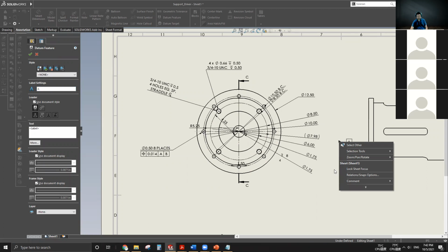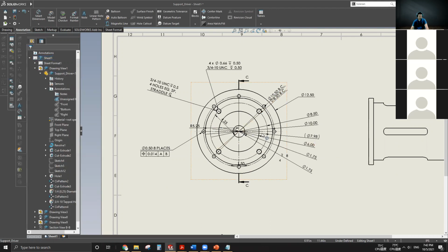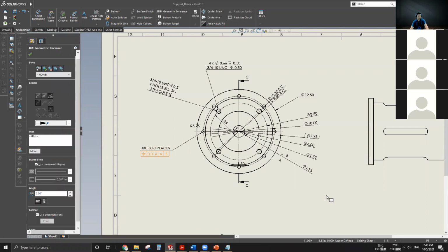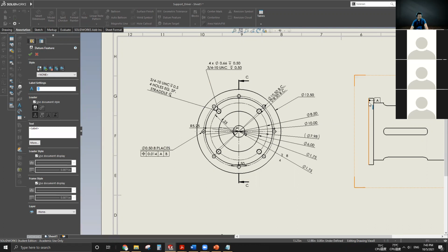Or drill it from there. So very commonly, when you set up a datum, you need to first consider what kind of tolerance is going to be referencing this datum. For example, if I'm setting this datum right here for the bottom plane of this object, I'll say this is my datum A.